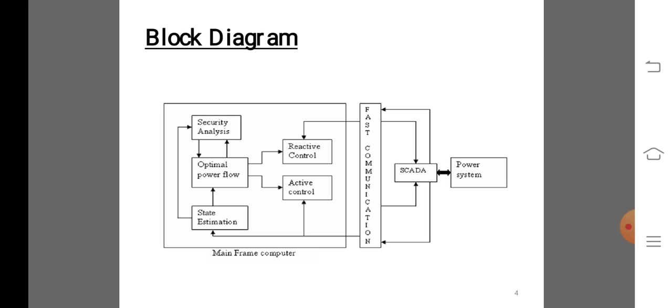Distinguish EMS from distribution management system. Both utilize their own SCADA but for different functions. Whereas EMS SCADA serves the high voltage bulk transmission system from the ECC, the DMS SCADA serves the low voltage distribution system from the distribution dispatch center. We are addressing in these notes this EMS and SCADA. It has an operation and control center that will be monitoring data acquisition and remote control.